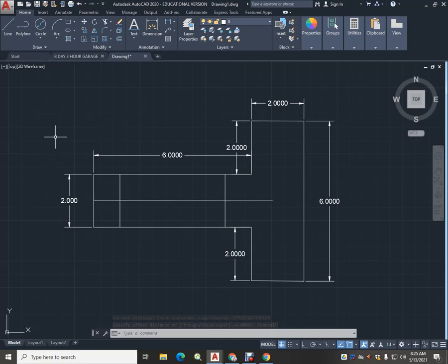So let's go ahead and make this slot. Remember that AutoCAD allows you to put in circles based on either radius or diameter, and the R is the symbol for radius, so we'll pick the radius, and our drawing part says 0.4375, and then we'll create the same one over here.